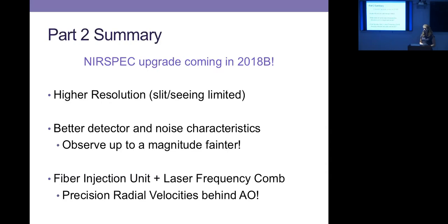But I think with the soliton you end up getting a broader spectral range, and then you can use these attenuators to try to get a flatter level of light coming out. For the laser comb, most of the light is coming out in just one short wavelength range, and you want to broaden that out so that you're not blasting the detector in one spot and hardly getting any signal in the other parts.